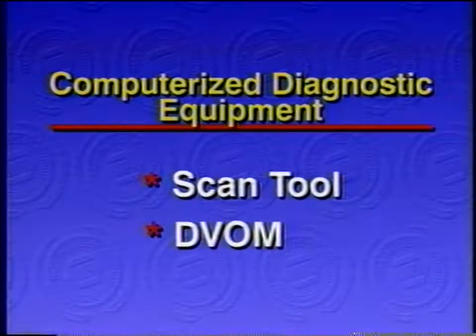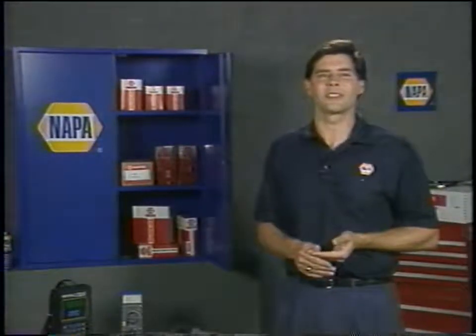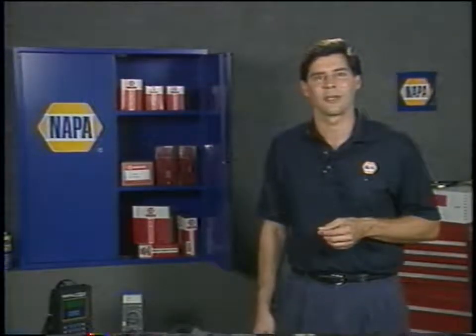Computerized diagnostic equipment is also available that combines the capabilities of a scan tool with those of a digital volt ohm meter to help you identify and pinpoint ABS problems. In addition to retrieving and displaying fault codes, some equipment has the capability of analyzing sensor data and other system inputs to flag obvious faults. Some test equipment also has the capability to perform various ABS system performance checks.